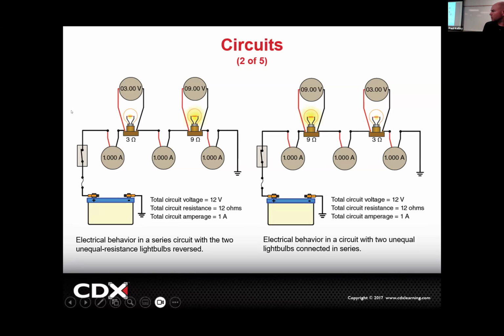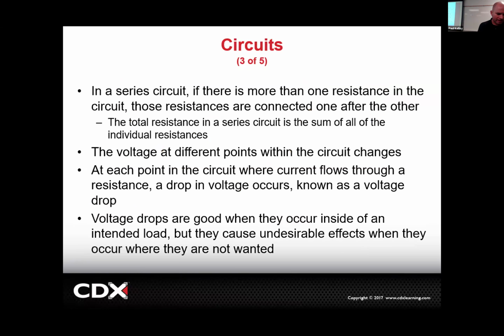So what'd be crazy is if you just ignored this bulb and you did these measurements, and this bulb right here dropped 3 volts and this bulb right here dropped 9, you could therefore, using your voltage drop, determine that there's 9 ohms of unwanted resistance right there. And you'd be like, oh, I need to do a wire repair, replace a terminal that's loose, replace a switch, something. Okay, that's where we're really trying to go. At that point, it's unseen. You have to measure it. You can't just look at it and only do what you see. Your eyes aren't going to be enough.